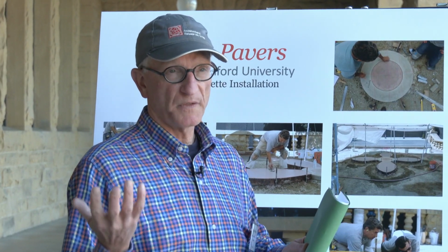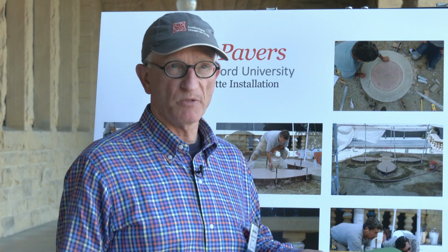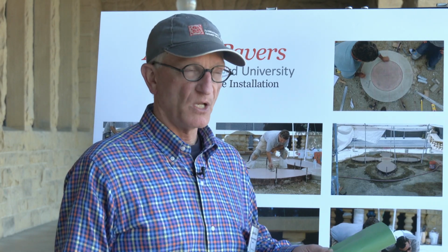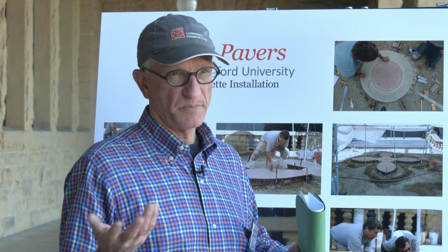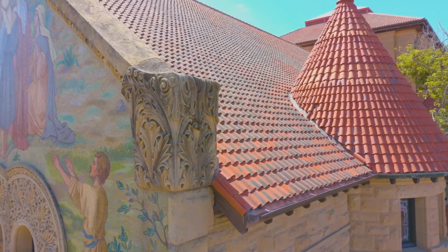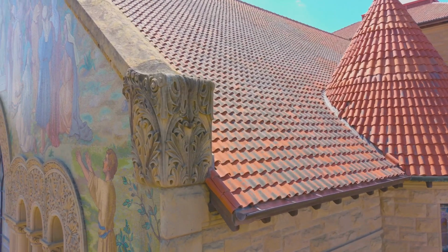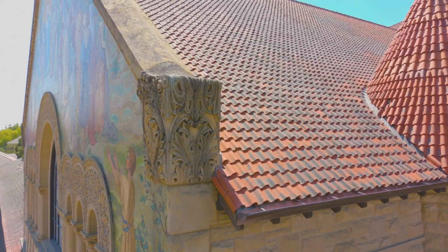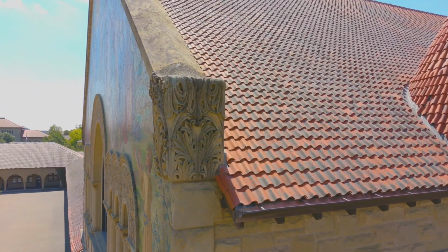And when we re-roof, it's the membrane underneath that needs to be replaced, not the tile itself. There is some breakage, usually 20%. That's because along the ridge and in other locations, the tile is mortared into place. So those tiles are lost.